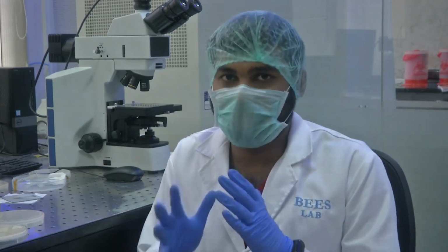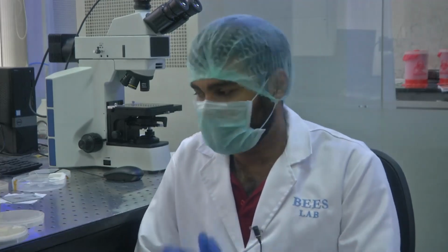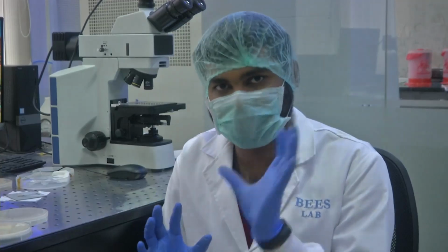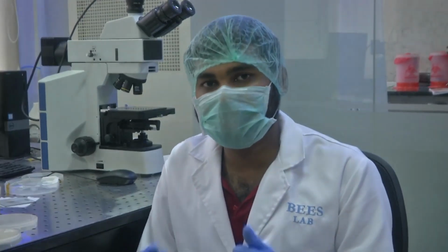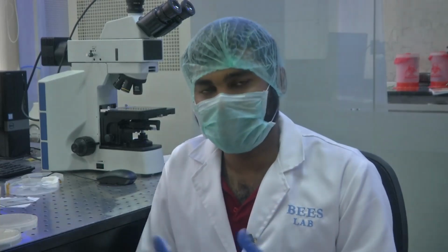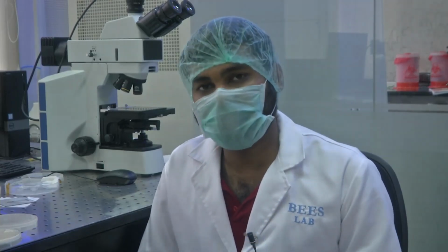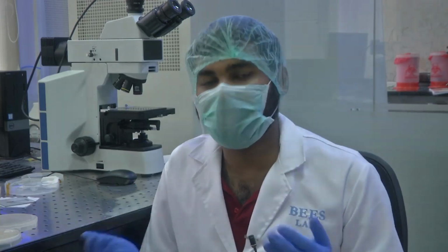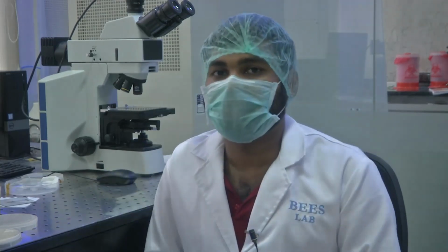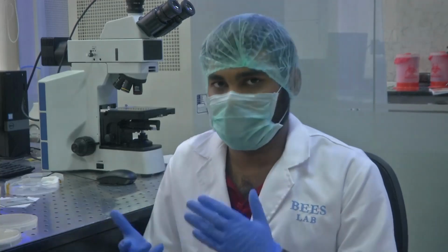So I think you understood what I have told you right now. We have shown you how a wafer blanket deposited with metal looks like. What is the design constraint? How much thickness of the metal was deposited? What is the requirement for a stiction layer or an adhesion layer? What materials will be used? And what is the design approach if you are making a microheater, and how it is different when you are trying to make an interdigitated electrode.